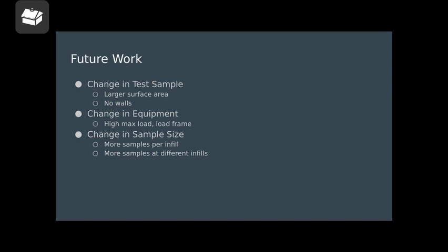Upon talking to Professor Hoover, we decided to come up with a taller test specimen that was thinner, which performed a lot better, but the surface area was so small that we ran into 3D printer tolerancing issues. So if this experiment were to be performed again, an intermediate solution would be best, something that is tall but a little wider to prevent some of those tolerance problems.